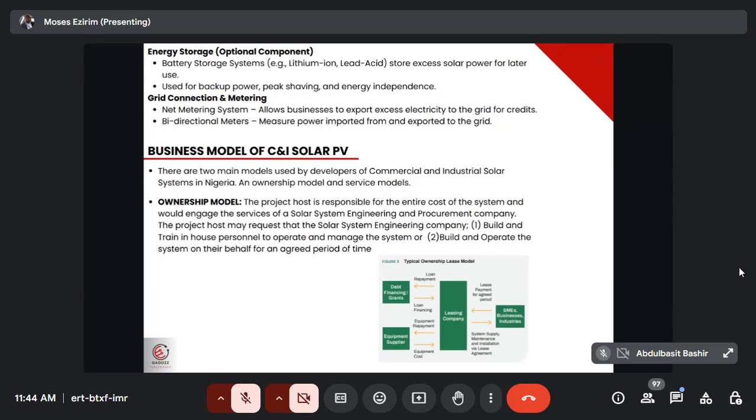So instead of your generator drawing 100% of that load, which is 700, it's now doing 25%. If you subtract 700 minus 250, what is it? 450. So if you integrate your solar into that system, your solar will be doing 450, and your generator will be doing 250.